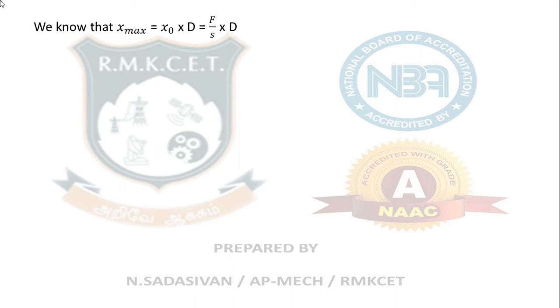So we know that x max is equal to x naught into d. This is what we have seen yesterday. Okay. So what did we see yesterday? x max equal to x naught into d. This is my static deflection and this is my maximum deflection. This is the example I initially gave you when I started. You place an engine on a chassis, it deflects by 2 millimeter. You switch on the engine, due to all the unbalanced forces in the engine, the deflection increases from 2 to 4. Now again you switch off the engine, the deflection comes back to 2.